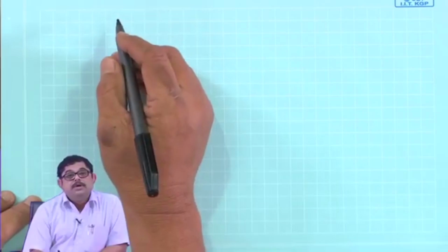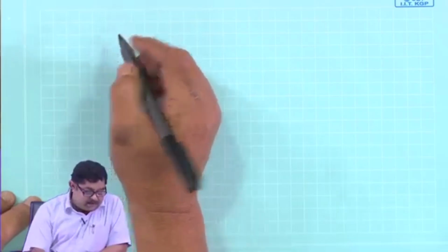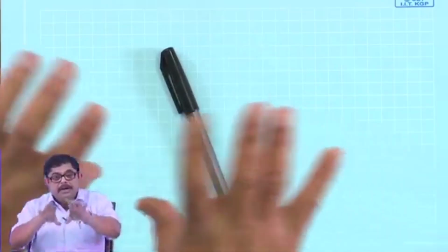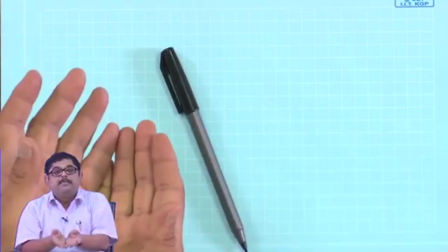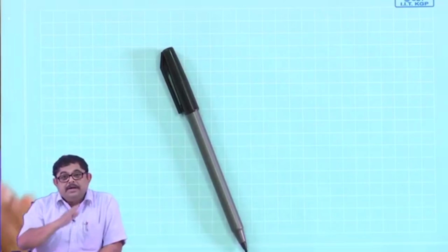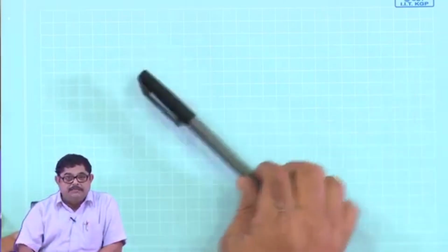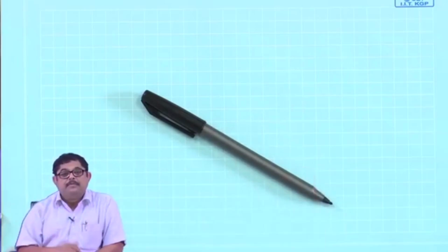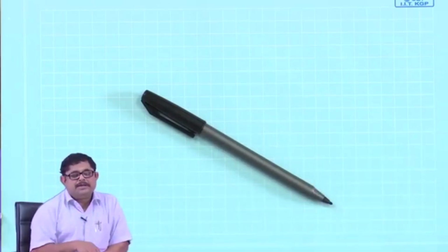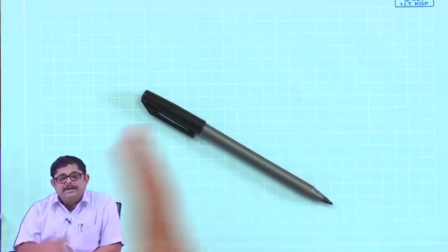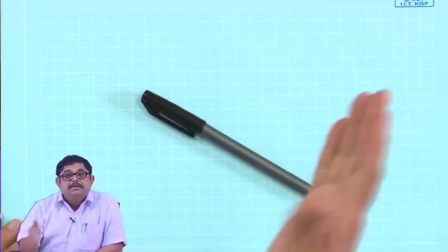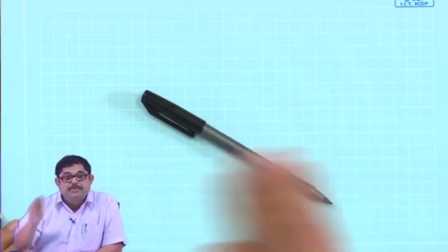Also, how to reduce RCS, that stealth topic I was talking about. There are various shapes; particularly in the geometrical shape of any body, if there is a discontinuity, that means the slope of the radius of curvature has a discontinuity, then there is a lot of scattering. So, stealth techniques require that the shapes should be as smooth as possible.